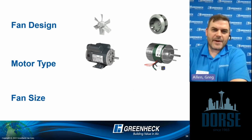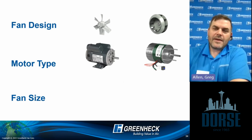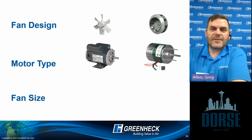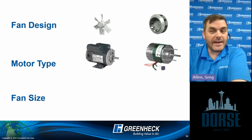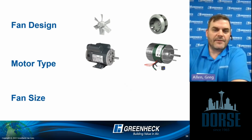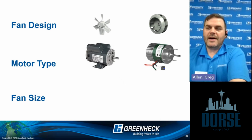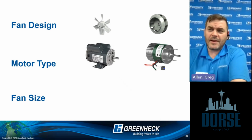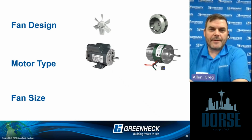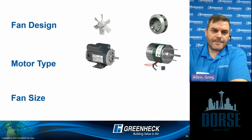Also under motor type, I kind of want to throw in VFDs with EC motors. VFDs and EC motors allow you an easy way to change RPM. So you can take a bigger fan, slow it down, and get into that efficient spot. Also, if you're doing a variable volume design for your building, I can move 2 different points of air, 3 different points of air: occupied, unoccupied, normal, and alarm. I have that range of capability because of the motor technology.